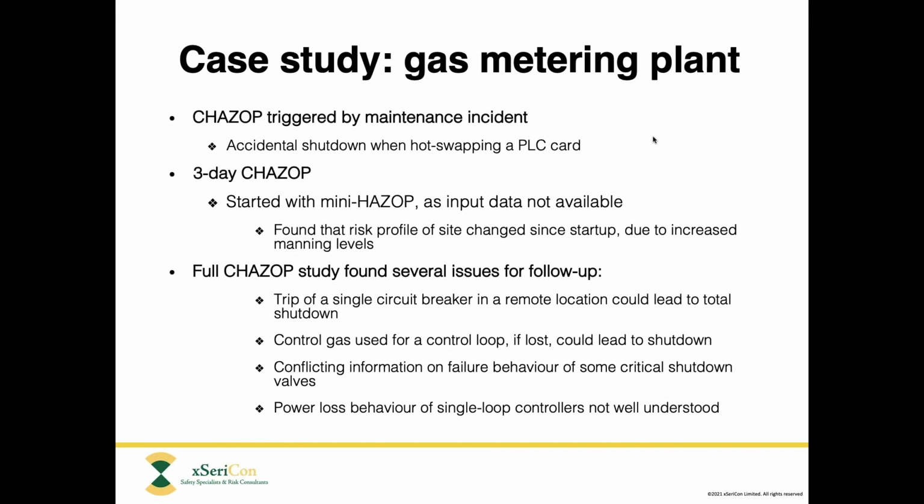In other words, there's a bug in it, and that bug results in a false zero output on the I/O cards. So maybe the software crashes, or maybe it gives a ridiculous result, like a negative number or something, which the I/O cards then interpret as zero and send the zero, for example, zero position to a control valve, or command a shutdown valve to close, something like that. So that would be the cause.